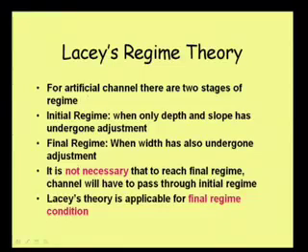Well, then another important point when we are talking about an artificial channel: there are 2 stages of regime. Till this point we were talking about regime condition, and the true regime condition, and what conditions we should have. But when we are making an artificial channel, there are 2 stages of regime. One is called initial regime and the other is called final regime.